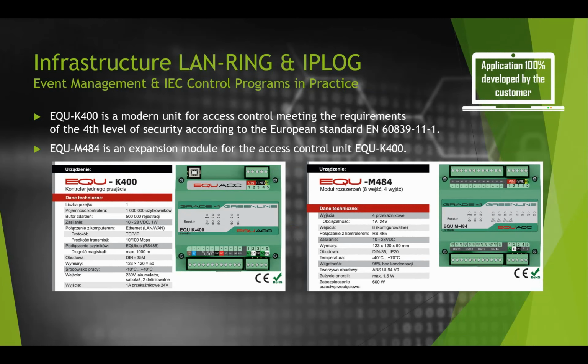The hardware of control units and I/O modules of the DIN series has become the basis of the access control system for objects with a high degree of risk. I say hardware on purpose because the firmware was developed directly by the customer. System security is, among other things, guaranteed by encrypted communication on RS-485 buses. The app also uses secure boot technology to sign and encrypt the firmware.